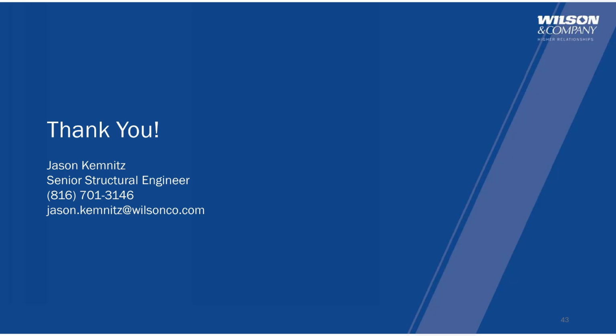I was the district bridge engineer for MoDOT for 1 year in Kansas City, so I do know that you do have scour at your end vents. Either it be a stream crossing or really a grade separation where you have bad runoff details or something that's coming around your abutment wings, right? Or truly under the roadway. It can sneak up underneath there. So then you have issues with drainage. So having those galvanized really is advantageous at that ground line for any water erosion that might occur, and really helps in controlling any deterioration that may occur, and any difficult details you might have to come back and have your maintenance crews tackle at a later date.